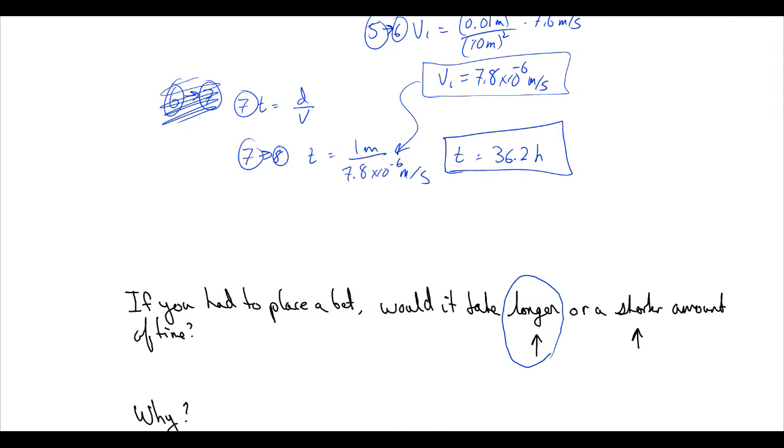You don't know exactly how big those errors are, but you know it has errors, and those errors will tend to make it so that the model's prediction is worse than the actual behavior of the system, if that makes sense. In this case, our model's prediction is less than what the actual system would do, and so our model is not conservative.